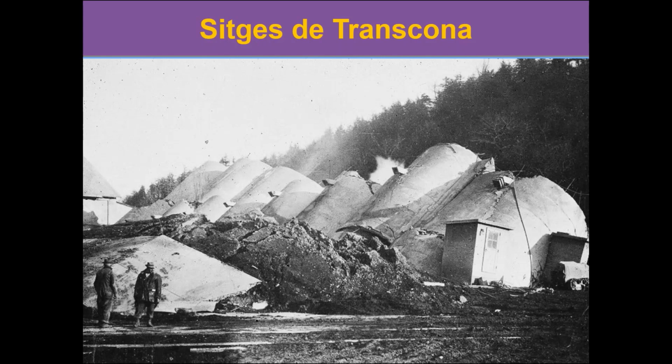We never act on the soil with axial tension stresses because we know that the soil is formed by particles, and particles are not able to take tensile stresses. So we try to compact the soil to produce a better strength, and we apply forces of compression because we know the compressive forces are taken by the soil. But the shear stresses are the stresses that make the soil fail at the end of the day.